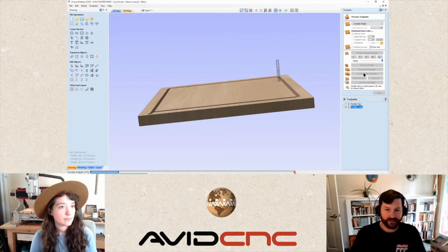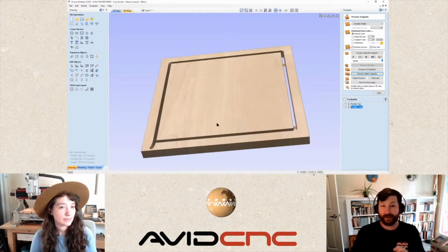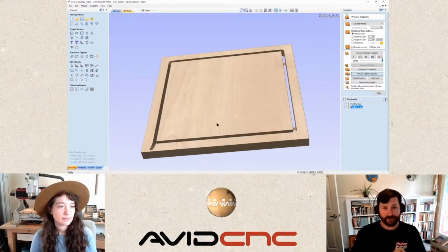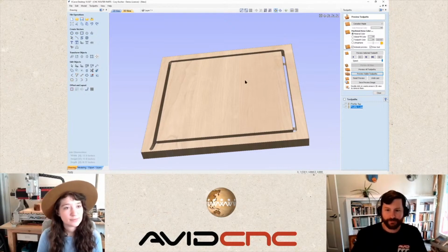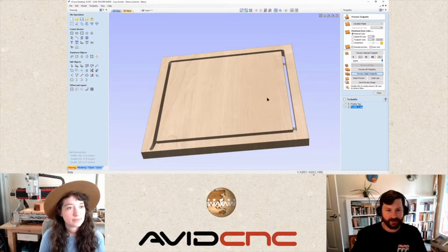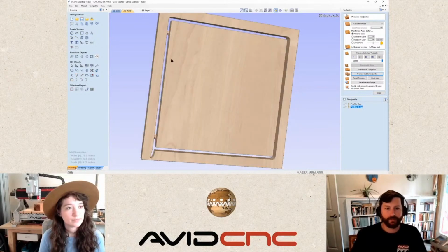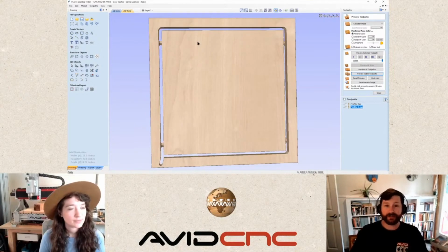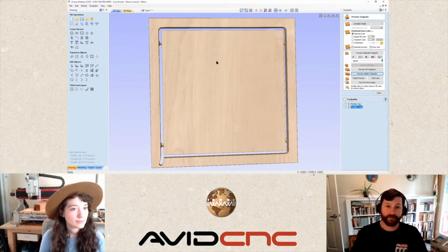And what you'll see here is we're going to go round and round. We're going to make this square. We're going to have the toolpaths. I really like 3D toolpaths because of the fluidity of the machine movement too. We don't get those hard stops. It allows for X and Y to continue moving. And yep, we have a perfect little 10 by 10 square here. This is going to be really high cut quality on both the top veneer and the bottom veneer, and it's going to operate in the machine very efficiently, getting that faster feed rate and getting the chip evacuation, keeping that tool cool, and allowing for you to get a better value out of that tool.